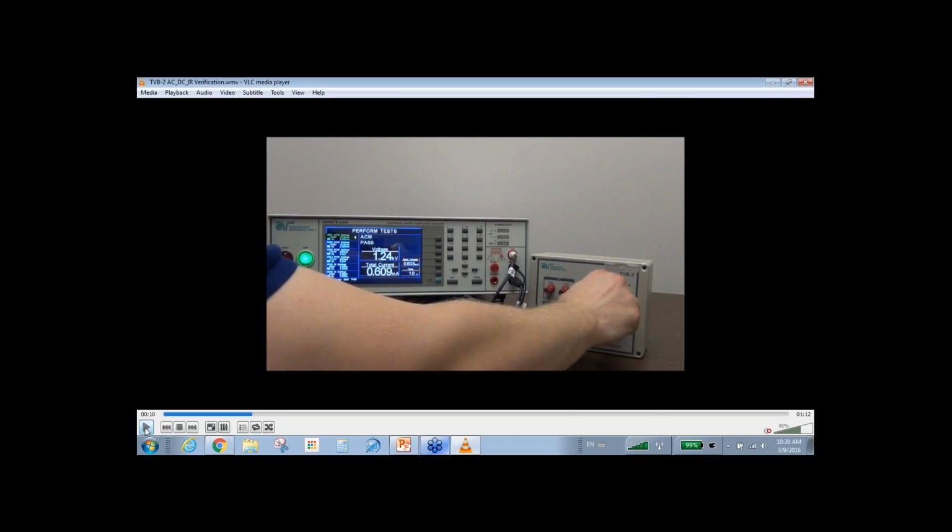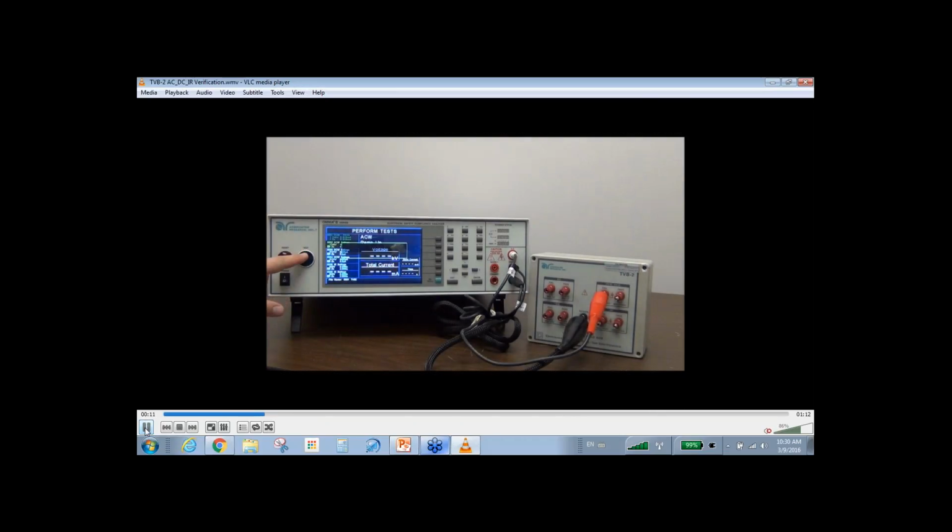So next we're going to try the high pot fail scenario. In this case, applying 1240 volts resulted in a high leakage current. Previously you saw it was 0.609 milliamp. Now the resulting leakage current is almost 10 milliamp.